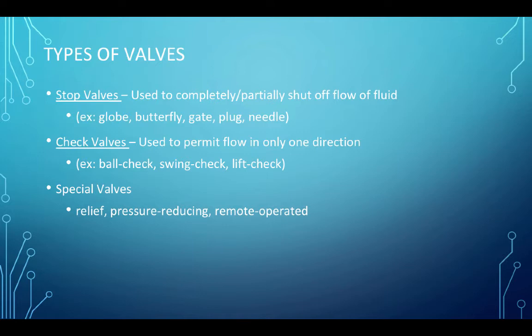Check valves are intended to permit flow in only one direction. The electrical circuit equivalent is a diode. The technologies in hydraulic systems are ball check valves, swing check, lift check, and I'm sure there's a few others.